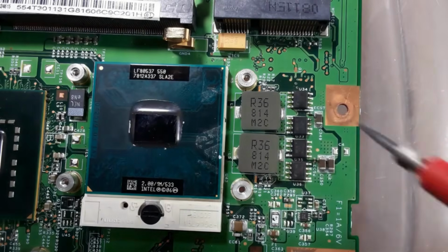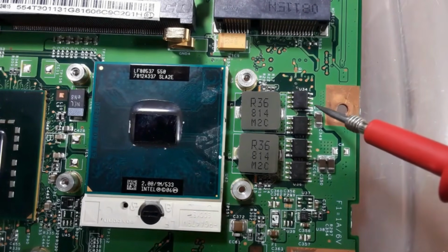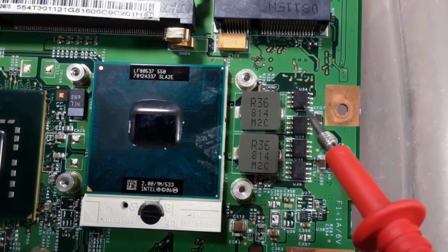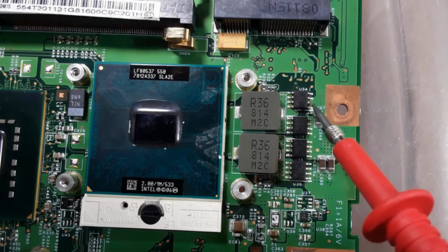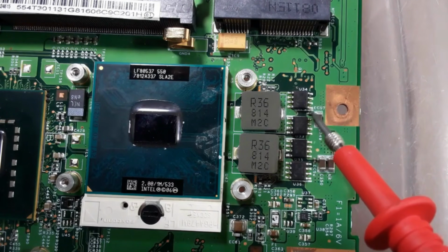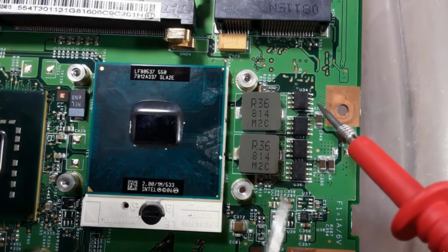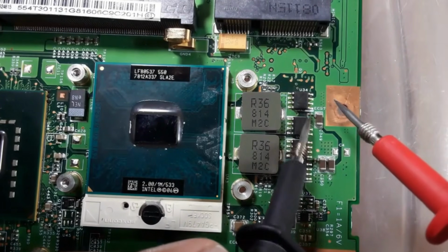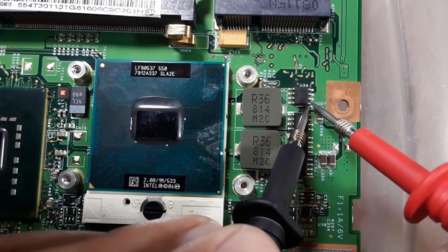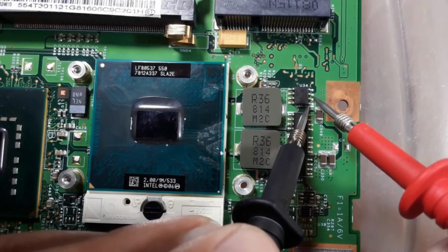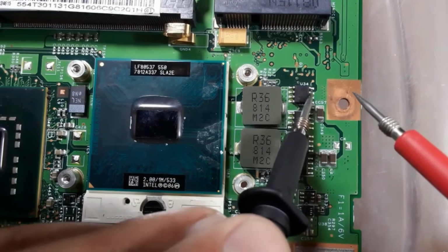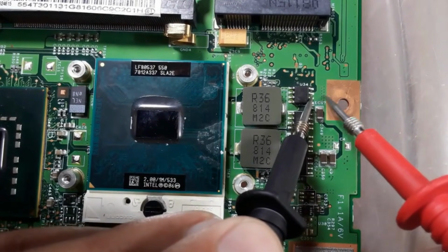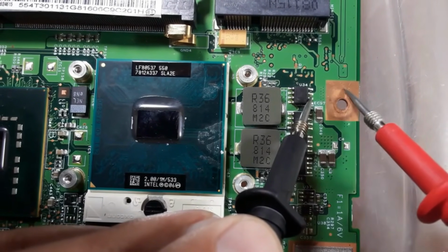also this MOSFET, as you can see, we have 3 terminals here. Okay, because here we have this point and this mark, which means this is the first pin of this MOSFET. First pin, second and third. So this is the source of the MOSFET. These 3 pins should be connected together, as you can see. So let's check these 3 pins. As you can see, these 3 pins are connected together and also connected, as you can see here, to the ground.